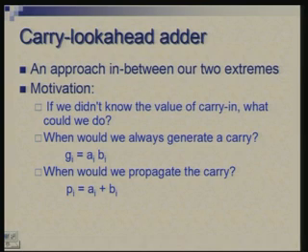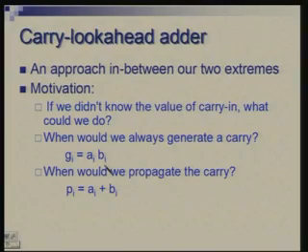In one stage, we will let individual circuits for each bit position digest AI and BI, compute something which is more useful, and then do what we tried to do in the previous slide. So, instead of computing CIs directly from A's and B's, we will compute them from some pre-processed form of A and B.